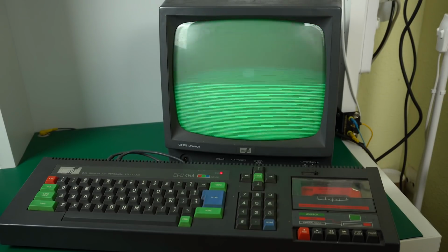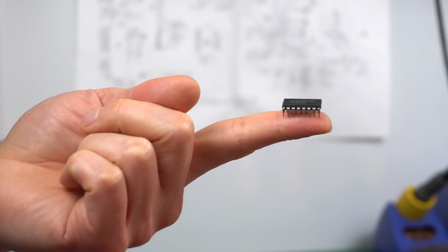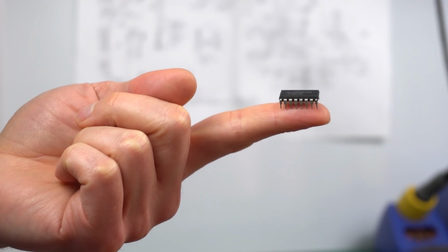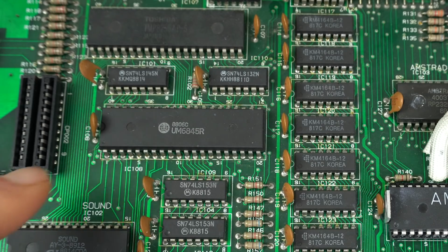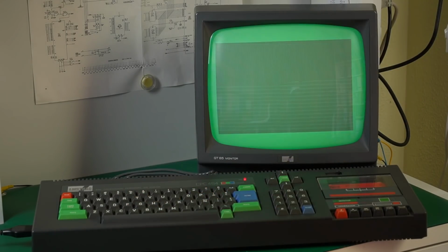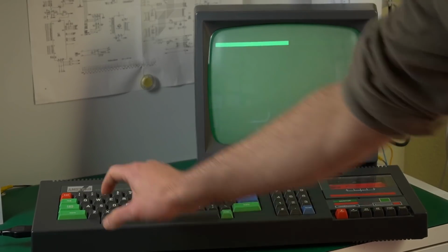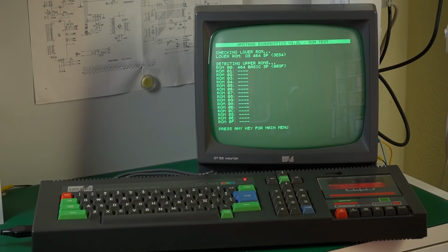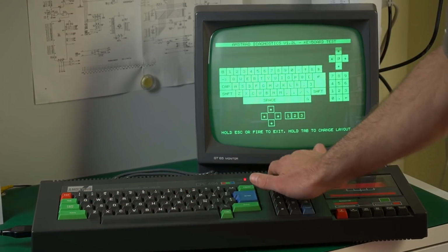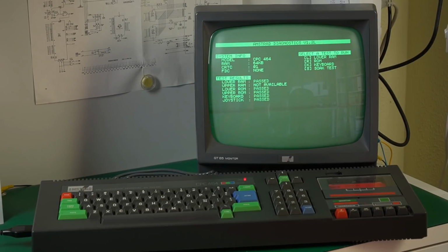So what I first thought was the main problem with the machine, it turns out was something totally normal, and the only real issue here was the faulty RAM chip and the fact that it was setting up random frequencies in the CRT controller. I gave the Amstrad a quick cleaning, and just to make sure that everything is working correctly, let's run the latest version of the diagnostics program. Lower RAM is fine, ROM is fine, and the keyboard and joystick all check out as well. Excellent, I think this machine is ready to go back to Marcos.